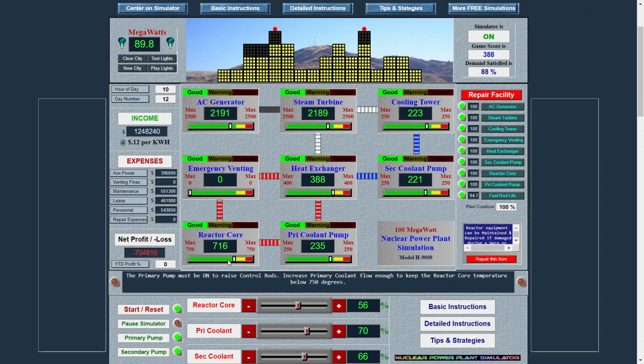And the reactor core is at 720 degrees. Let's increase primary coolant. It's a bit hot. And now we see most of the indicators are at their optimum, so at the end of the green range, without incurring yellow range in which you can start damaging your material. I will increase a bit secondary coolant to see if I can increase a bit the power in the turbine.